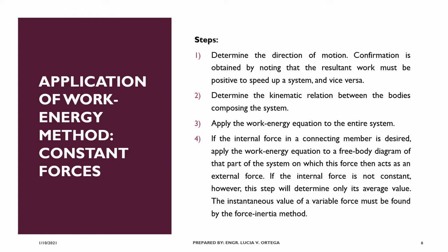If the internal force in a connecting member is desired, apply the work energy equation to a free body diagram of that part of the system on which this force acts as an external force. If the internal force is not constant, however, this step will determine only its average value. The instantaneous value of a variable force must be found by the force inertia method.